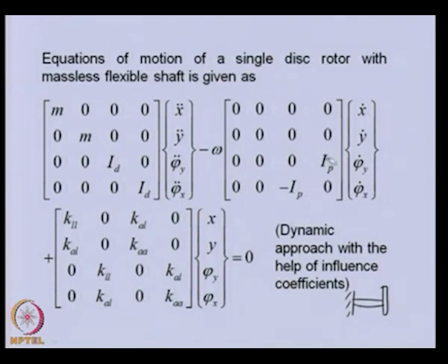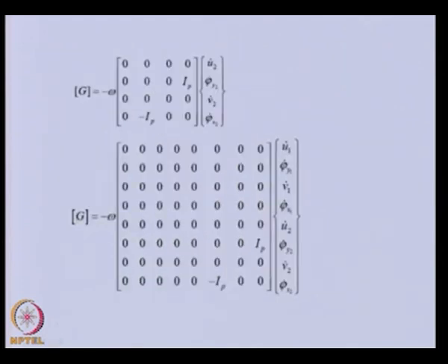So, we are taking this separately, but we will see that the stacking of the displacement vectors is different here: 2 linear displacements and then angular displacements, but in the finite element formulation we have 1 linear, then angular, then linear, then angular for node 1 and 2. So, let us see that particular gyroscopic matrix in our finite element field variable stacking.